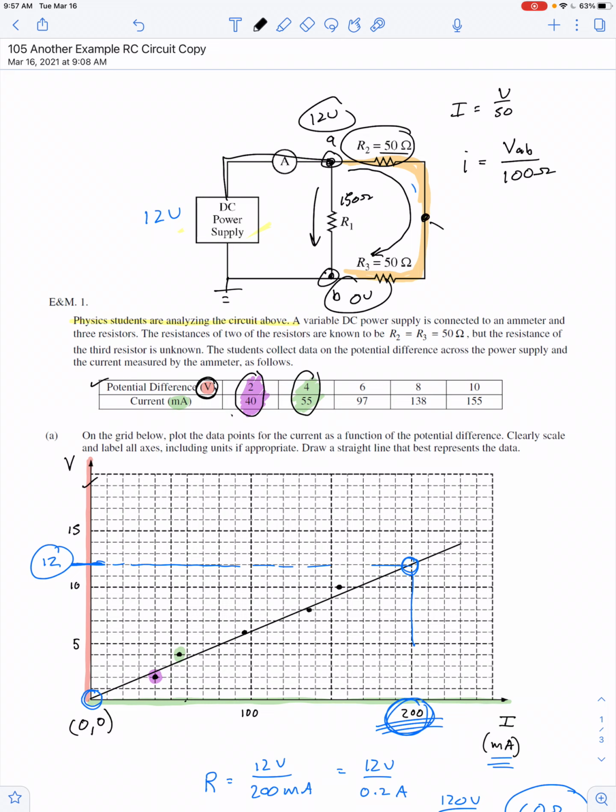See, I don't know what the electric potential is here. Well, actually I do. I know it's 6 volts because these two resistors are acting like a voltage divider with equal values of resistance, so it divides the voltage in half. Anyway, in general, I wouldn't know the value of that electric potential if these were two different value resistors. So what I'm using is the resistance on the whole path and the voltage across that whole path to find the one value of current through that path, right?